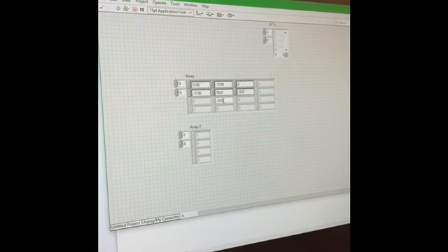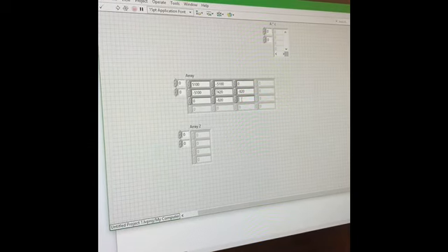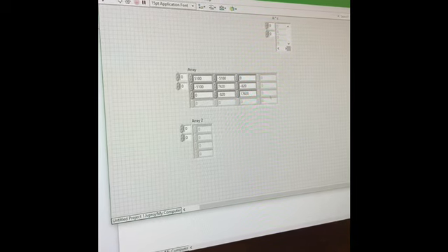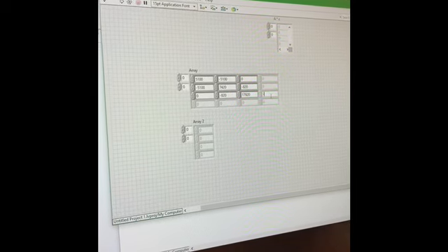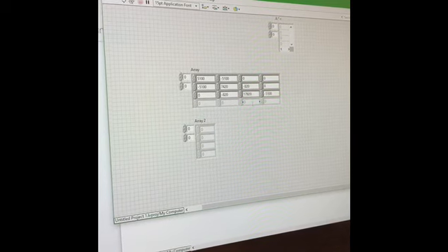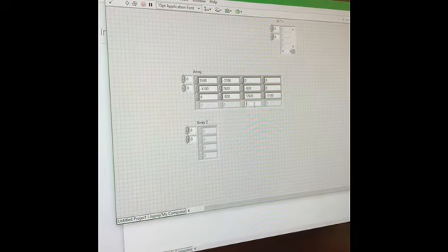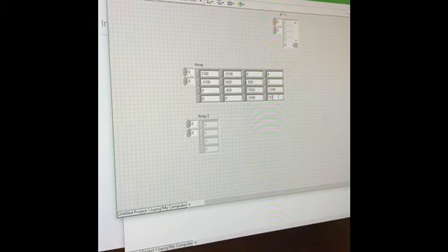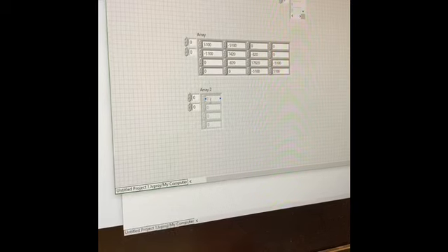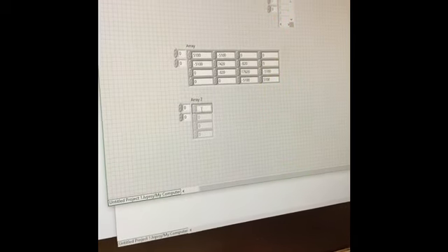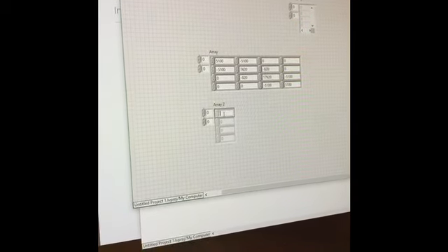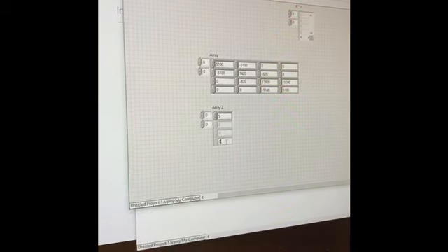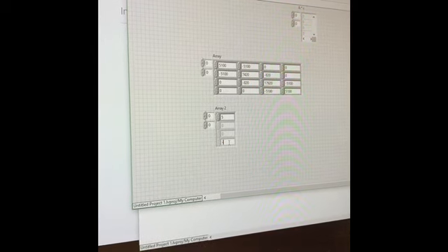The third loop, we're going to have no I1, so we'll go to I2 and we'll have negative 820 ohms. And with I3, we'll have 17,920. And then I4 is with negative 5,100. And the fourth loop, we have negative 5,100 with I3 and a positive 5,100 with I4. So that's for the left side, and then we go to array 2 for the right side. And we have 5 volts with the first loop and negative 15 volts with the fourth loop.